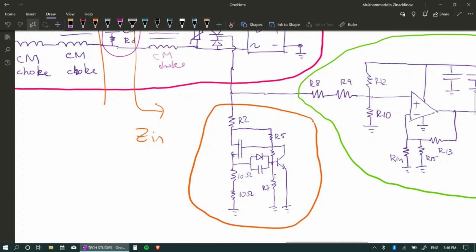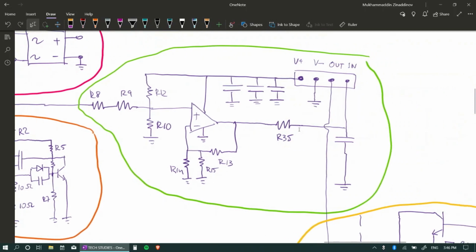So there is no controller switching these transistors. We see that some current flows through this MOSFET, and we have some sensing resistors here. The current in those sensing resistors is picked up by this BJT. The BJT will conduct more or less current depending on the current that flows into the base. So this voltage here will be higher or lower depending on that. This here is primarily for stability purposes.